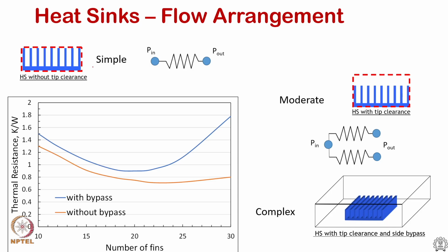So, here is a situation where we talk about a heat sink. There is an airflow. This is a front view of the heat sink. Air is going into the page like this and exiting the heat sink. In the side view, the airflow is entering and exiting. These are side inlets. The top is covered, and the bottom is where the heat is applied. Heat is dissipated from the base of the heat sink all the way into the fins, and the fins transfer the heat to the flowing medium. This makes the arrangement somewhat simpler for the further discussion.